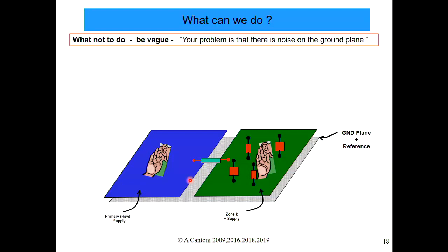What will happen is that as logic levels switch, they will have to charge or discharge capacitances or drive transmission lines. So you often get very strong current being drawn from the power supply in very, very small amounts of time. If the actual power supply system is not designed properly, then the localized voltage around those pins can drop quite significantly. That can also cause a problem for the device itself, and for other devices around it due to the power supply, but it can also propagate as noise around the plane.